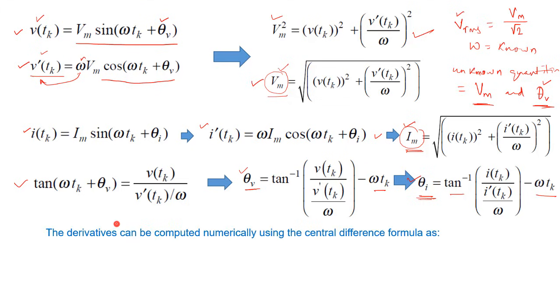So now the question is how to find these derivatives, the derivatives of the voltage and current signals. Derivatives can be computed numerically using the central difference formula.